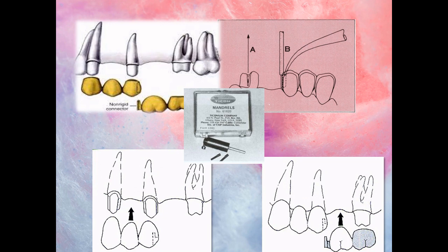It is removed from the working cast. It is invested, burned out and cast. And after the casting is recovered, then the mandrel and any excess portion on the top of the key are carefully reduced so that the key and keyway are flush.